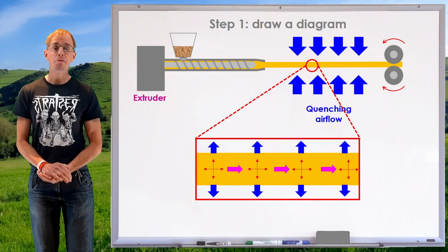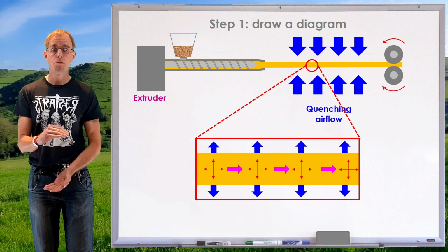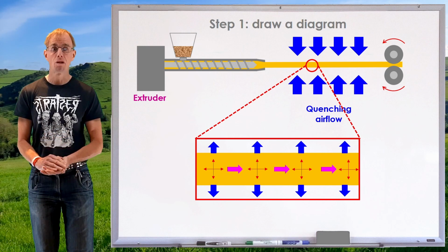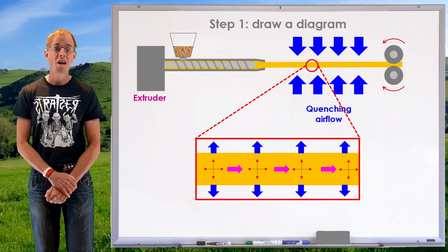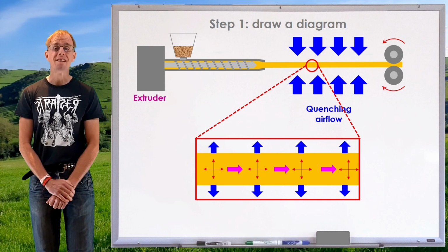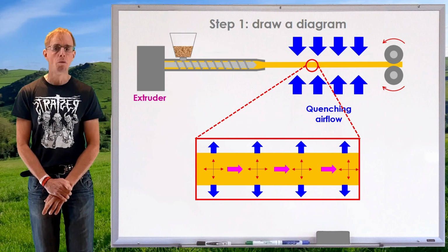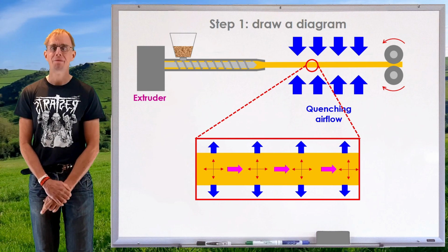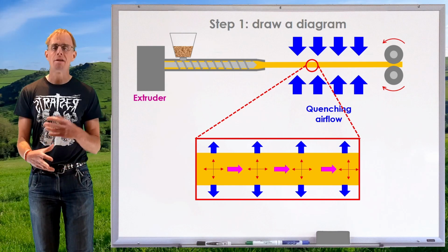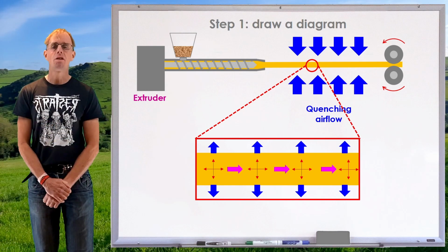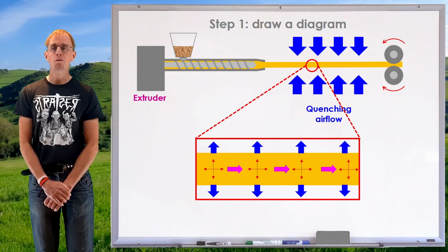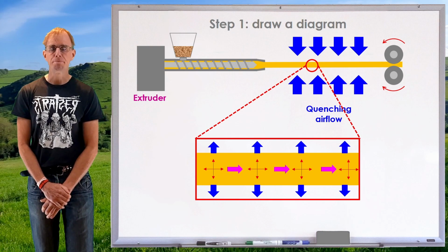I can also have heat flow up and down. So I've got a thick product, I've got a poor conductor of heat, I'm likely to have a temperature gradient in the convection direction within the product this time. And so we can sit down, we can draw our diagram, we can understand what's going on in terms of the various processes of heat transfer.